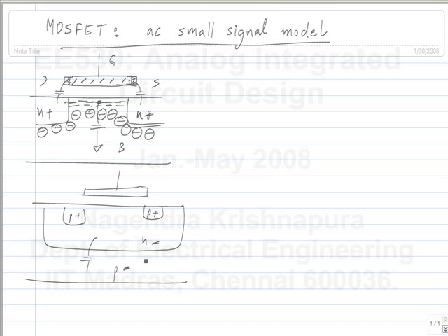This is something you have to take into account, especially when you are not connecting the substrate of the PMOS transistor to some fixed potential like VDD. If you connect it to VDD, then the capacitance will be between VDD and ground, and it's not as important. It is particularly important when you don't do that and, for example, connect it to the source. If you connect it to the source, obviously this capacitance will be from the source node to ground.